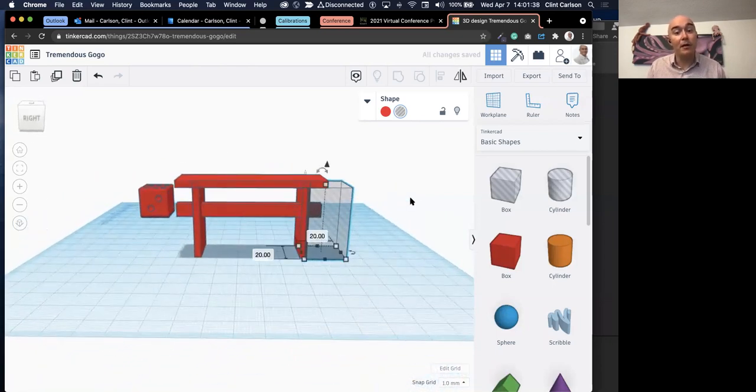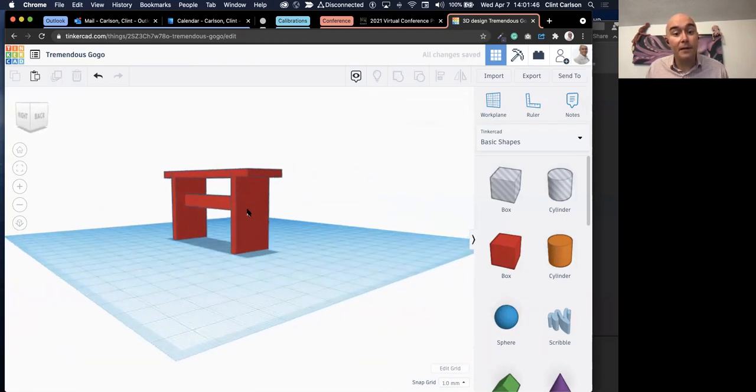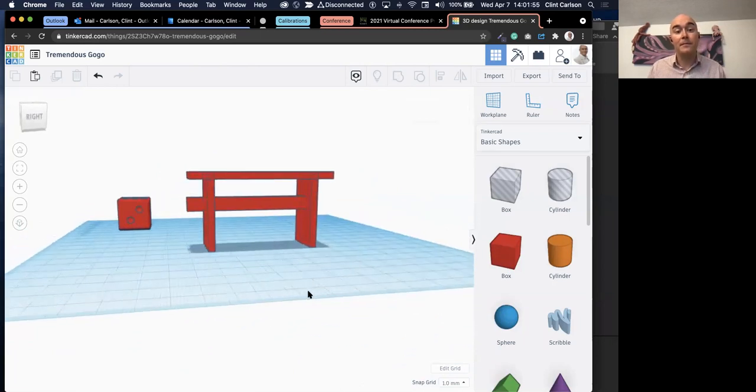It's okay if it intersects with that leg because I'm not going to cut off the leg, just this barrier bar. So I've selected this hole, selecting that support beam. I'm going to group them together and cut that right off. And because it intersected a little bit inside of this leg, the cutoff of that is happening inside of the leg itself. So we don't see any seams over there.